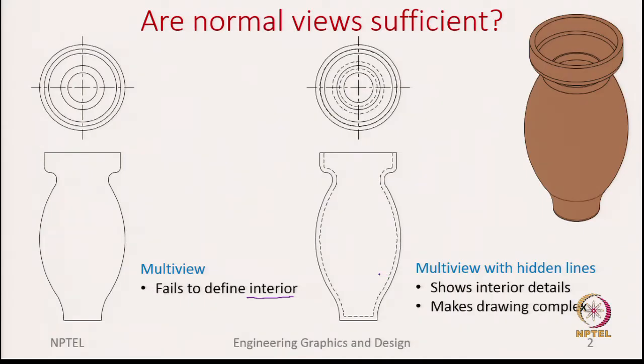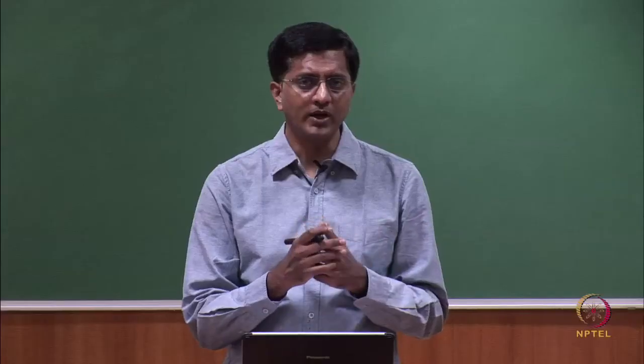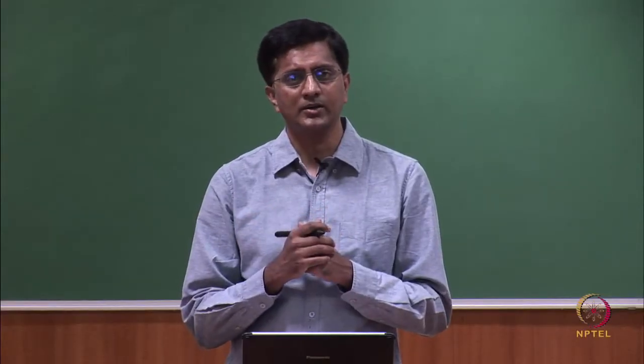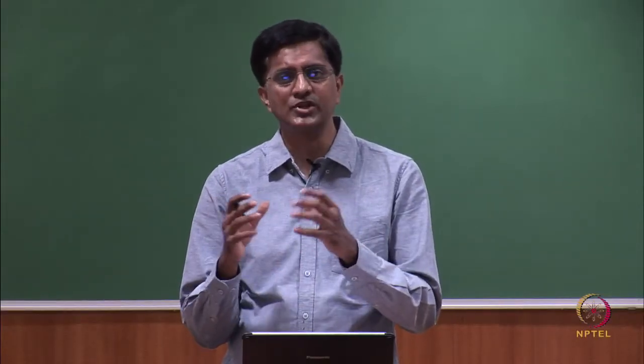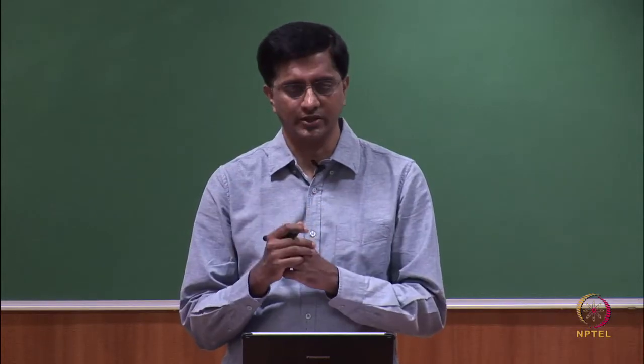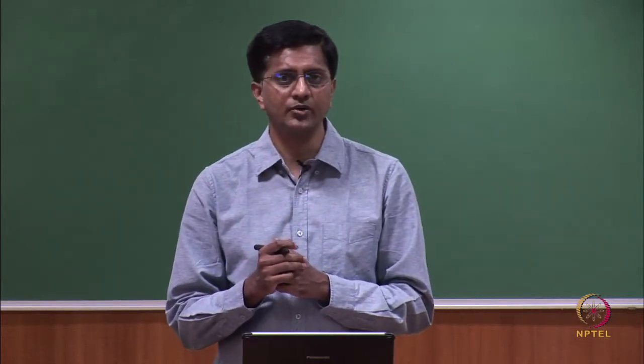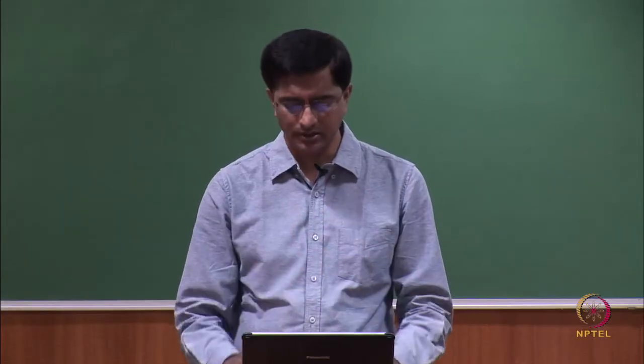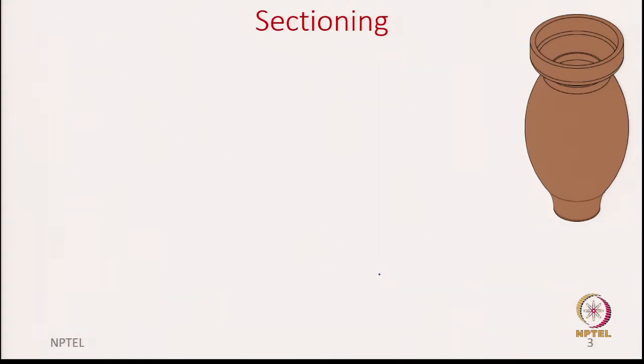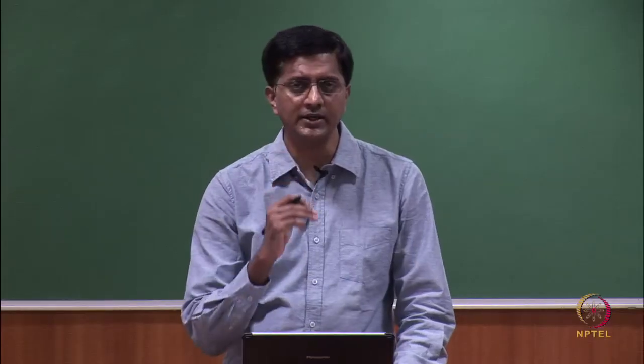But the point is, the more and more hidden lines you use, the drawing becomes complex and then it becomes difficult to read. So, this might solve the problem, but it may not really make an efficient drawing or a simple and elegant drawing. So, let us see what is the other alternative we have to show these interior details. So, we will be discussing sectioning, which is a technique used to show the interior details.